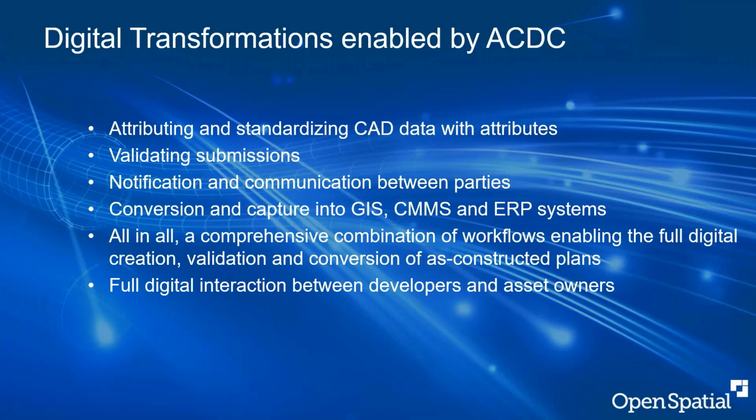That includes attributes, it includes spatial characteristics. Well, let's go with topological, in other words, nodes and links and lines and connectivity between them. And then you can look at even relationships in those. So if you're doing a gravity network, yes, we can look at upstream and downstream invert elevations and check that all works. We can also do spatial things like simple stuff, things like if you have a roadway, the name of the roadway needs to be within that particular roadway polygon.